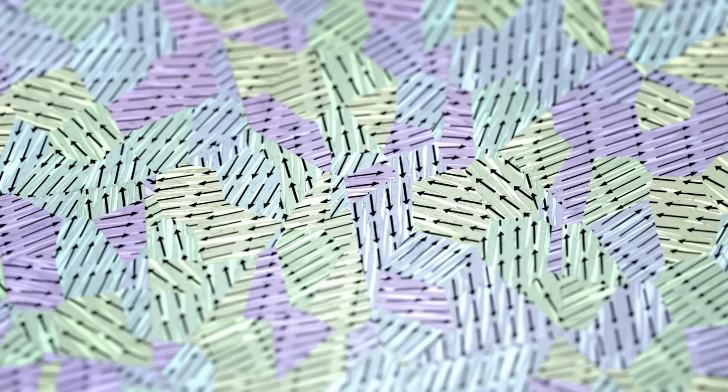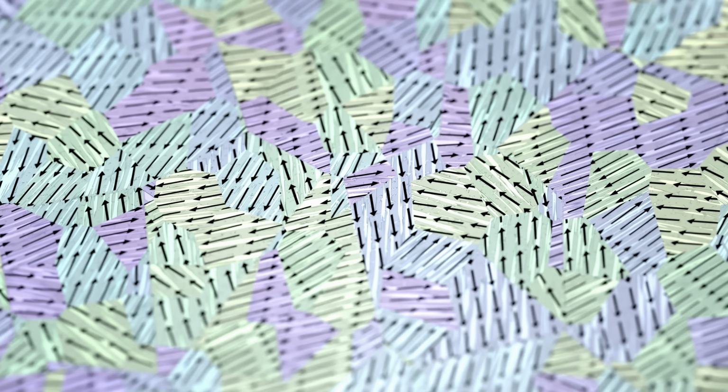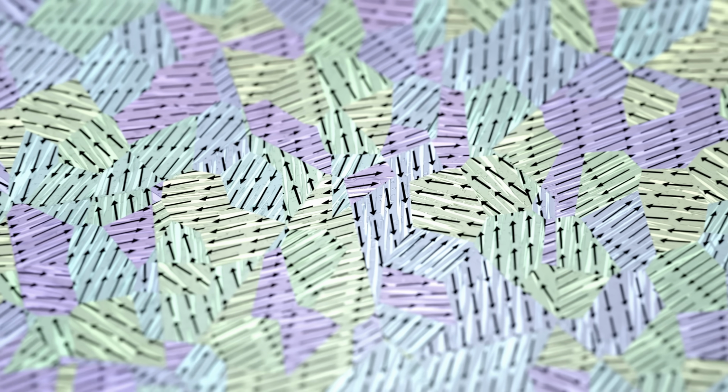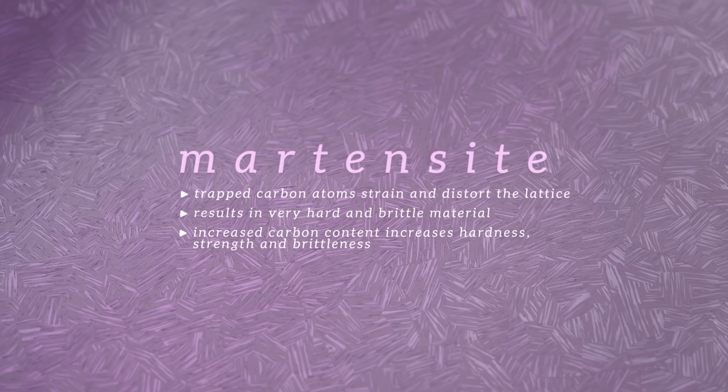The distorted lattice of martensite makes it an extremely hard and strong, but also very brittle material. This is due to the trapped carbon atoms, which strain the lattice, locking the structure in place and impeding the motion of dislocations. The steel's carbon content has a big impact here. More carbon means greater distortion of the lattice, which increases hardness and strength at the cost of increased brittleness.